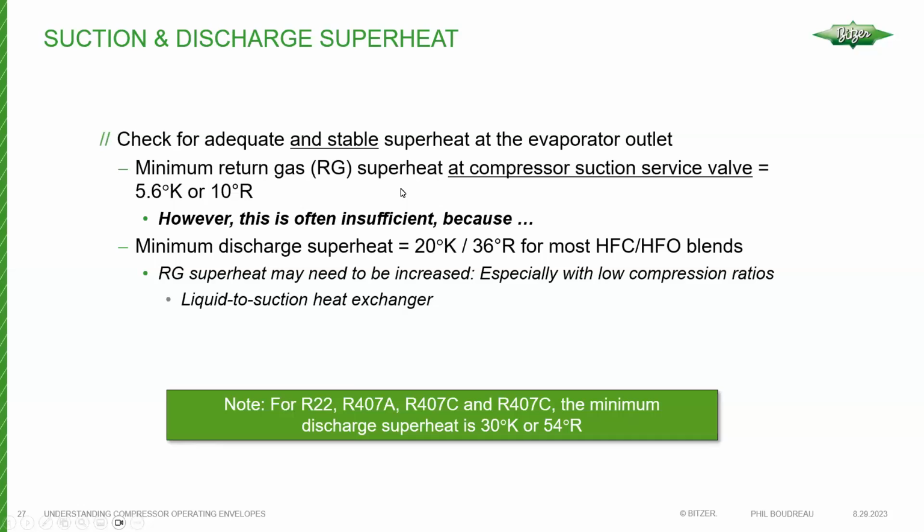So in this case, there's really not a lot working for us in terms of getting rid of that droplet of liquid after it leaves the evaporator. So it's absolutely essential that the superheat is formed in the evaporator, and enough of it, to ensure that we've got good, stable operation, good evaporator control, and of course, protecting the compressor at the same time.